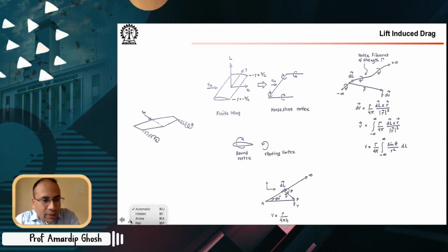This is also something that we have discussed in the previous class. You can find the velocity field induced at a location using the Biot-Savart law. And this is the Biot-Savart rule that is useful for our discussion, because remember, for us, our vortex line, or rather the vortex filament, is curved and it extends from minus infinity to plus infinity.